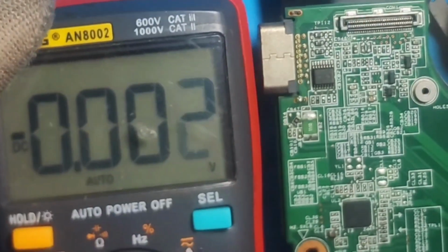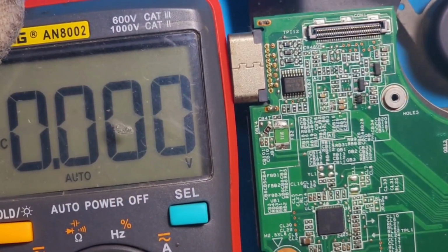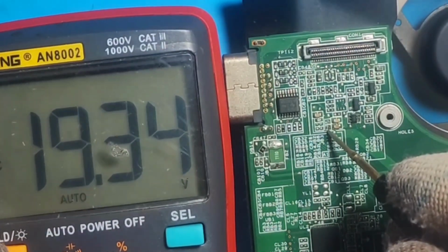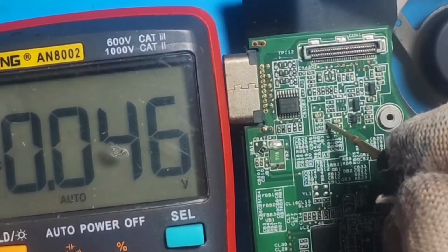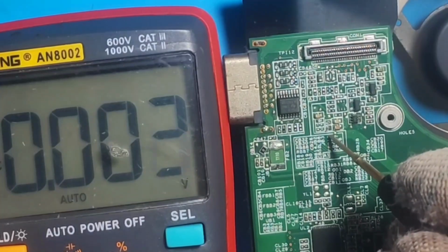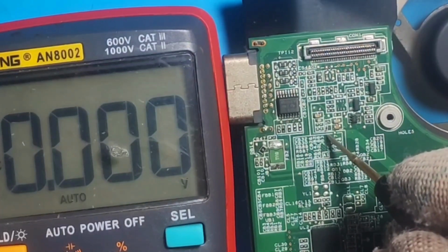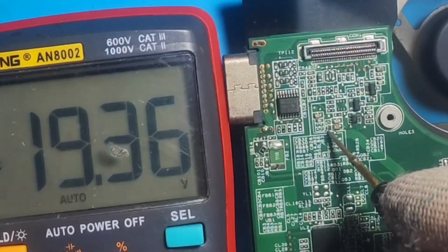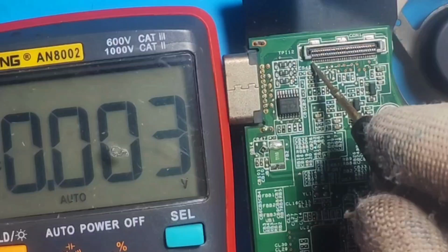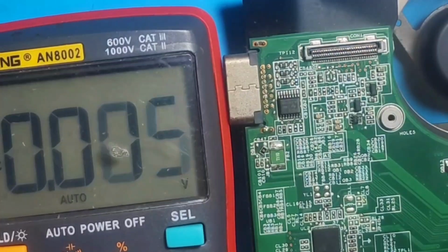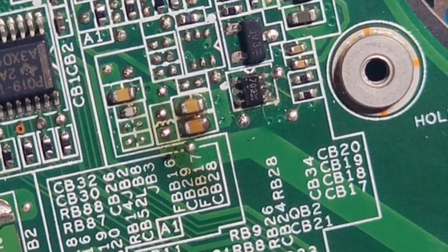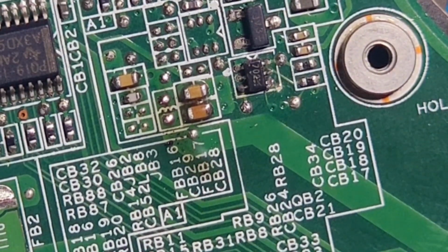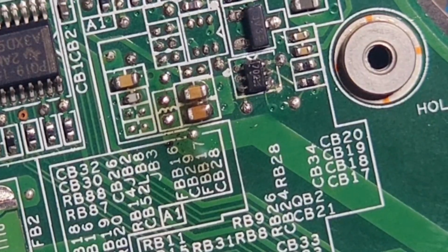the voltage on that side. So on both sides, I should see 19 volt on this side. Yes, we are getting 19 volt on this side. On the other side, we are not getting any voltage. So this is the coil that switches the 19 volt from the current sense resistor to the LCD circuit here. So it is missing. So that's why we are not getting the 19 volt at pin number 30 and pin number 29. Okay, now that looks fine. Let me place a new coil in that place so that we can get 19 volt on the display connector.